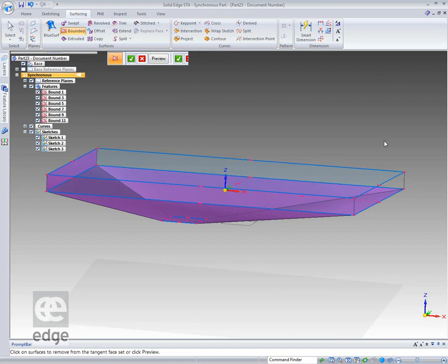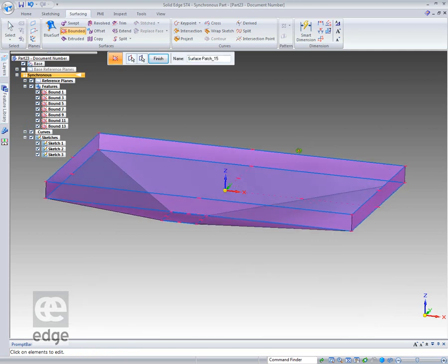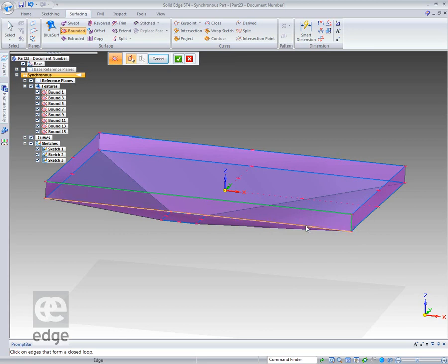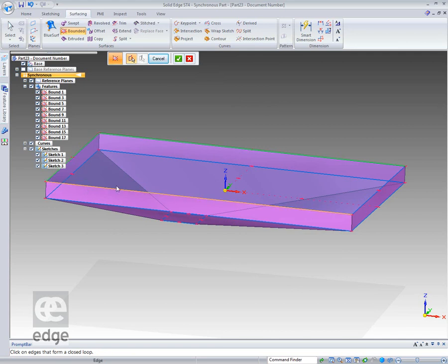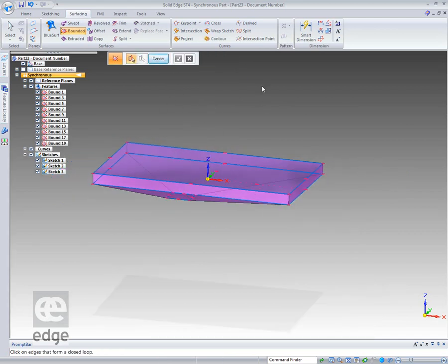And one more. What I'm doing here is actually producing a set of boundaries, if you like, that will define how the solid model ultimately will go together. Now the thing we need to keep in mind while we're modeling with surfaces in Solid Edge is it does use the Parasolid surface kernel to build these, so we know that the surfaces we're going to create are manifold. So when I click edges that are on top of the edges, they will in fact join and they will make a solid. So all I need to do now is stitch all that together.